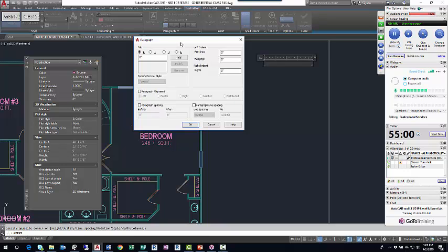And what is this paragraph dialog box? Well, what I'll do is enable something called paragraph spacing. What paragraph spacing allows me to do is to give the appearance of having double spaced paragraphs. So I'll have note A, and then the text that supports it, and then 2 spaces, note B, the text that supports it, and so forth. To use this, I just check paragraph spacing, and the max value you can put in here is 4 inches. People will sometimes get upset when I say that, and they'll say, well, how do I know 4 inches is the max? Well, if I put 6 in here and try to OK out of that, it's not going to let me put anything smaller than 1/4 inch or larger than 4 inches.